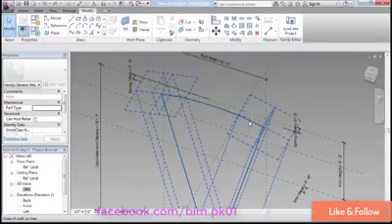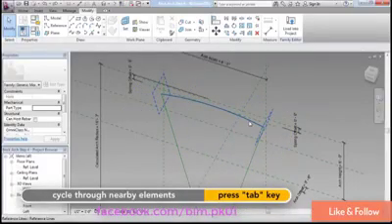I showed you that in the very first movie in this chapter. Also, you may recall that if you highlight a shape in the massing environment, it actually chain selects by default. So right now it's highlighting the entire chain of walls, or this entire pie slice, and it looks really busy. Just remember to press the Tab key, and that's how you can reach in and select just an individual edge.